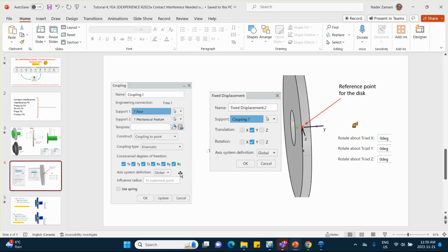And the same thing down here. I'm pretty sure if you uncheck these rotations, it will not make any difference. Because rotations are not degrees of freedom for the solid element, tetrahedral element or brick element, these are unnecessary. For example, you can uncheck this, run it, no problem. Or you can uncheck these three, run it, same thing. All right?